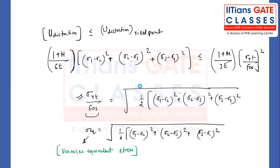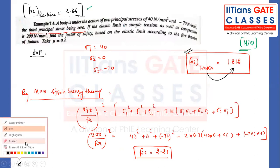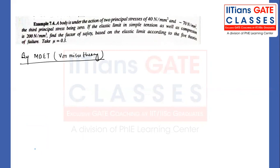Now we will solve the same numerical that we have discussed, by using the maximum distortion energy theory, the von Mises theory. Understand very carefully. So here once again, what is the formula we have? Sigma equivalent, or we are calling it sigma yt divided by factor of safety, that is equal to what?